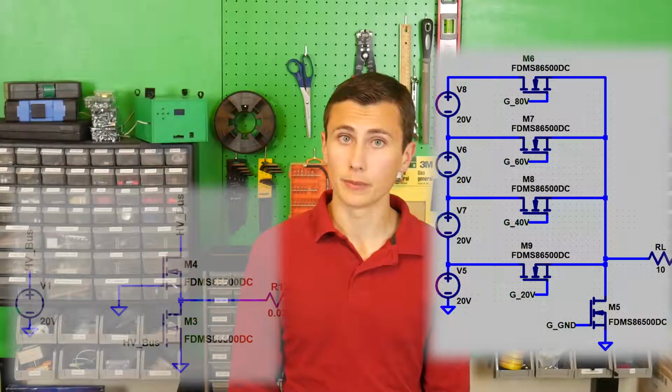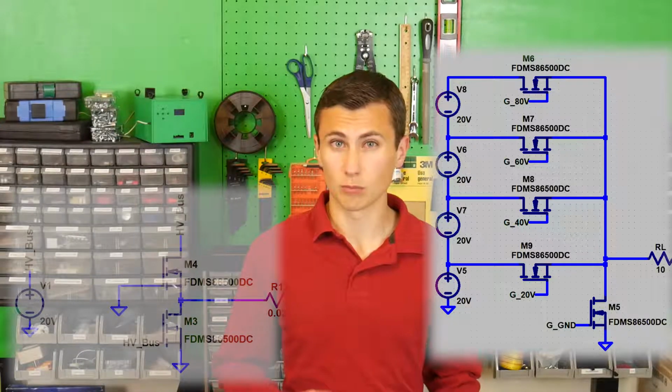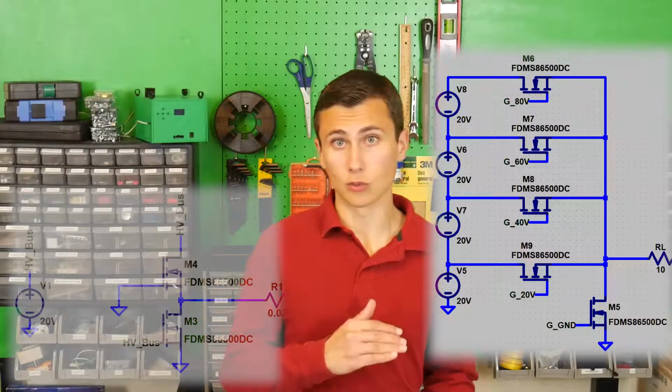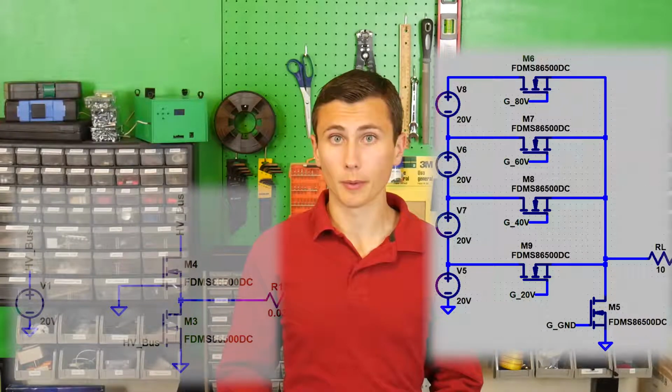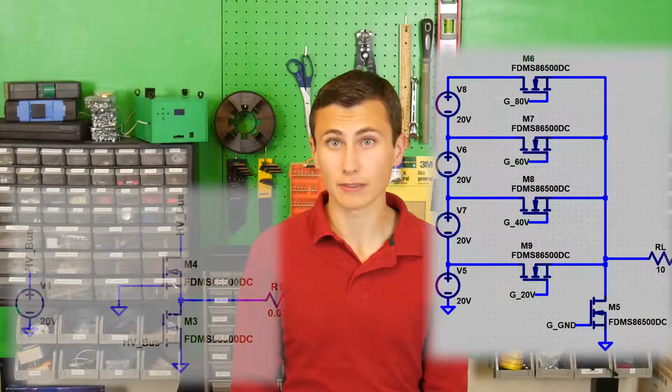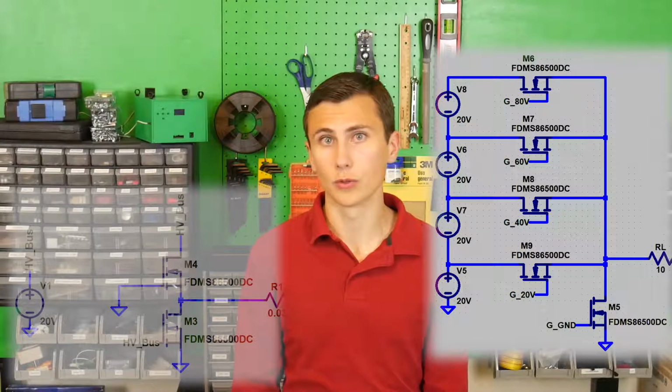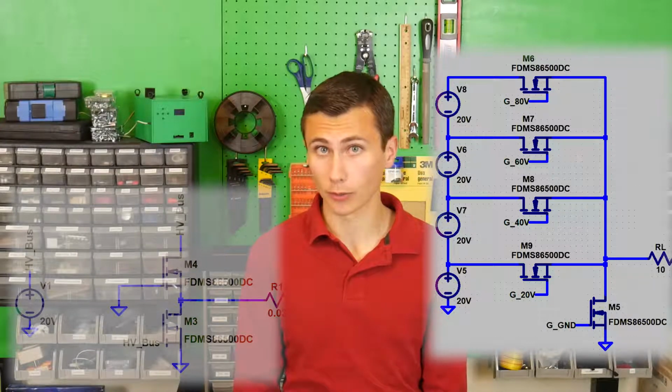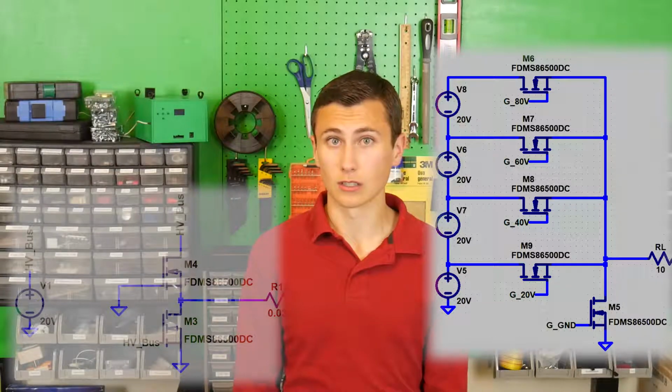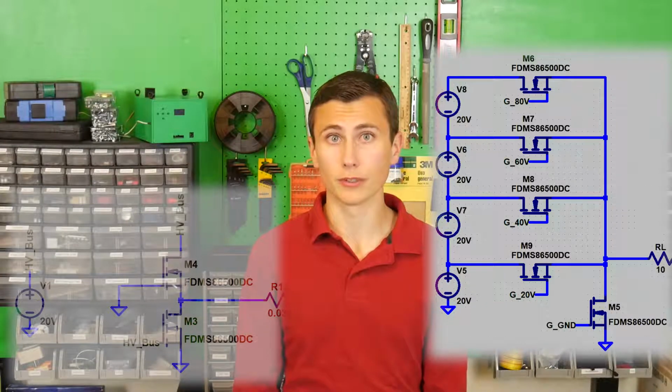Since our PWM is extrapolating between smaller jumps rather than VCC and ground, the ripple on the output of a multi-level voltage source inverter can be significantly reduced as well when compared to its two-level voltage source inverter counterpart, since there's less noise in the signal before it actually gets to our power filter.